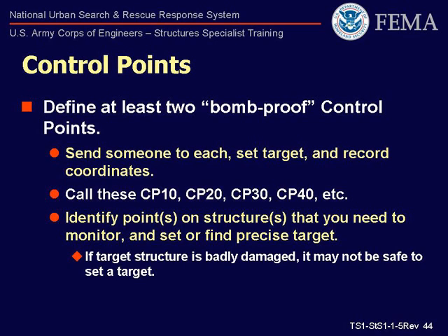Identify point or points on structure or structures that you need to monitor, and set or find precise target. These points will be called MP100, MP200, MP300, and so on. Above all else, though, understand that if a structure is badly damaged, it may not be safe to set a target on that structure, and all that can be measured is the structure itself.